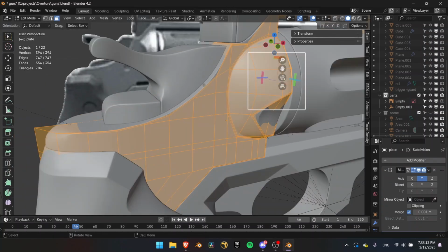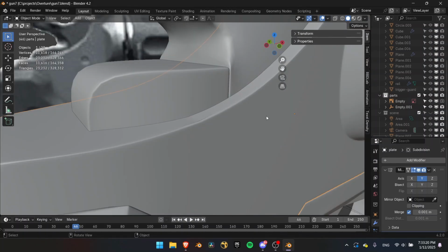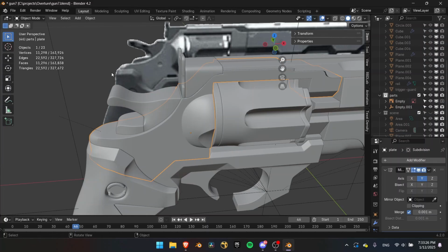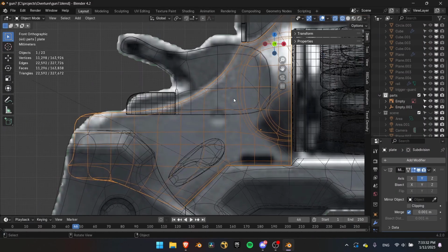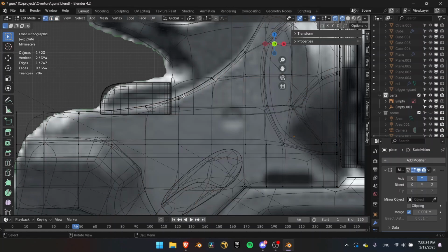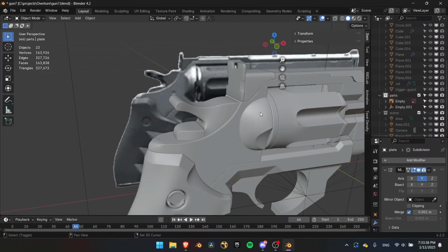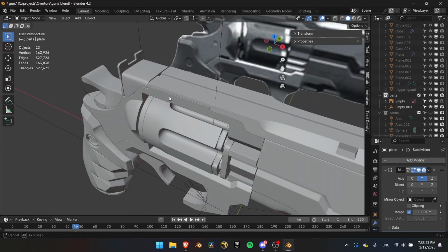Some of these smooth curves here, these don't have bevels. You can't add a bevel like that and make it sharper, but I just didn't bevel those, and it gave a nice smooth curve. I wasn't too worried about being accurate with the reference image here when creating these points, making sure they line perfectly with it, because I knew that it would just be smoothed out and then shade smooth in the surface. So this just had my back right there.